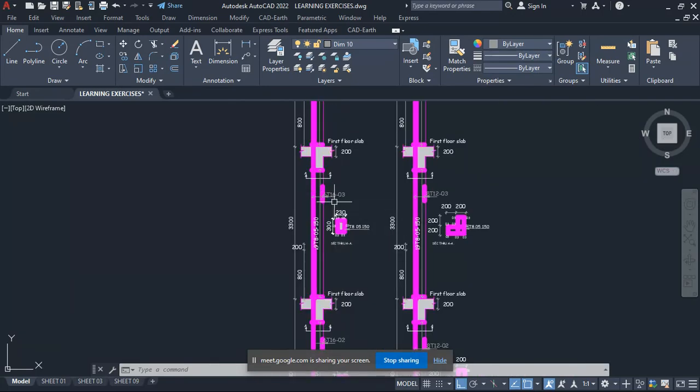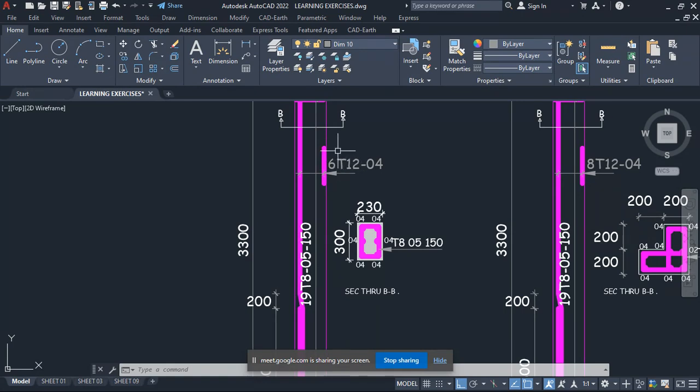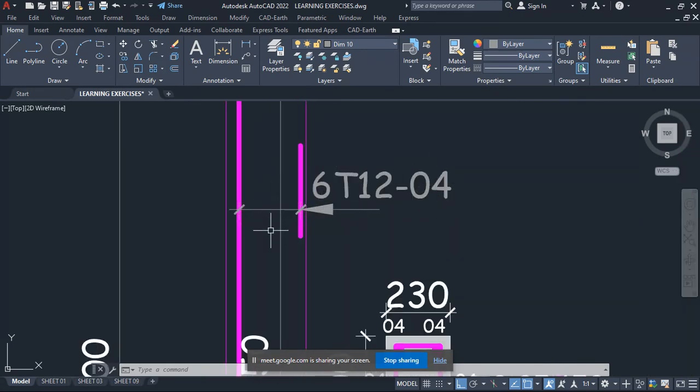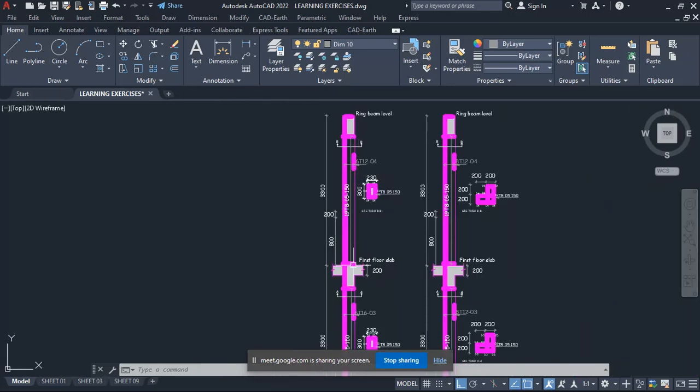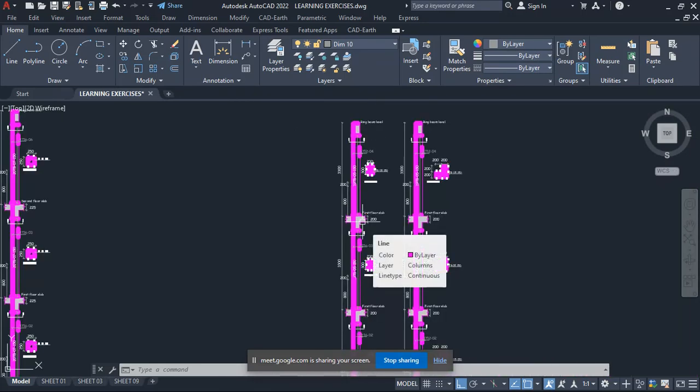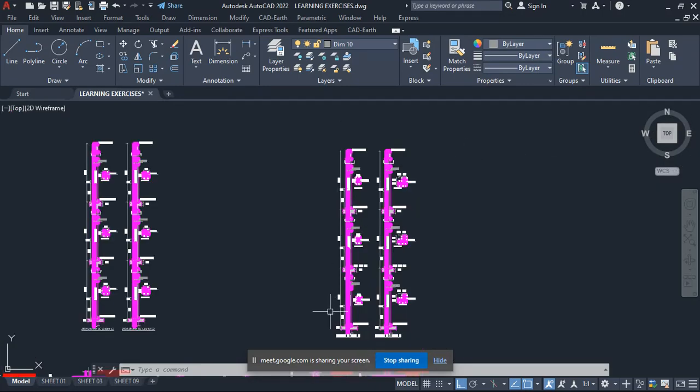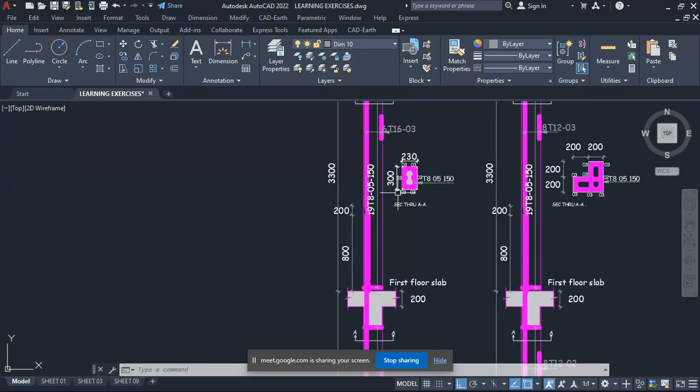So these bars could reduce actually, like when you come to the third floor where we have small axial load, could reduce from our frame analysis. If you still have it, I will show you that at this level, this was the actual load. At this level, at this node, this was the actual load. So you can pick those actual loads and shears, and you design them separately. So, any question about the column design and analysis? No, I understood. You're okay with it.